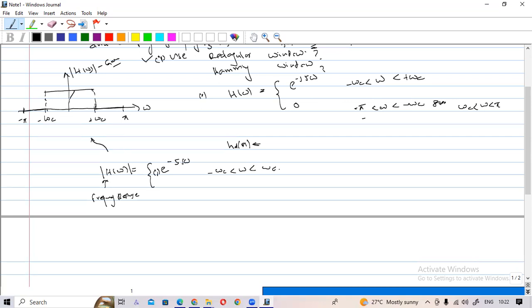So this is the low frequency range, and this will be a low pass filter. Actually, this is an ideal low pass filter. As I told you, practical realizable filters are like this. There can be some ripple, and the slope is not sharp. So you have this kind of slope, then again some ripple may be there. And yesterday I told you that depending on this function, the filter can be categorized in many ways into another three types. We have discussed this in the recorded session, so you can refer to it.